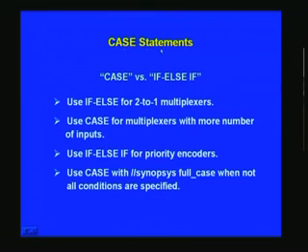Now to summarize this and make a comparison between case and if else if, it is listed here. We have already seen if your intention is to make a 2 to 1 mux, use always with if else statement, and if you want more than 2 inputs, you use case statement, right. If you want priority encoders, we have already seen if else if, and if you want to have a Synopsys full case or parallel case, use case here, right. And full case is used when not all conditions are really specified, that is what we have already covered.